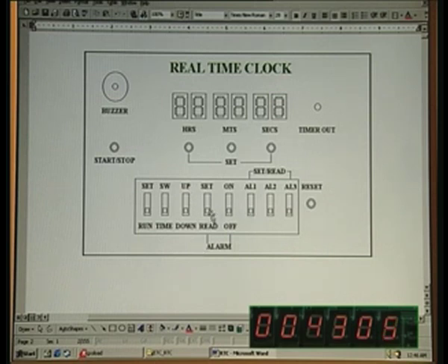So these two are earmarked for alarm. You can switch off the alarm or switch on the alarm. This is only to switch off the actual audio alarm. This does not really reset whatever you have set, and you can set these alarms. For example, there are 3 different alarms that you can set, alarm 1 through alarm 3. Of these, topmost priority is AL1, alarm 1, and AL3 is the least priority. If you take to this position, you would be setting or reading the respective alarm.